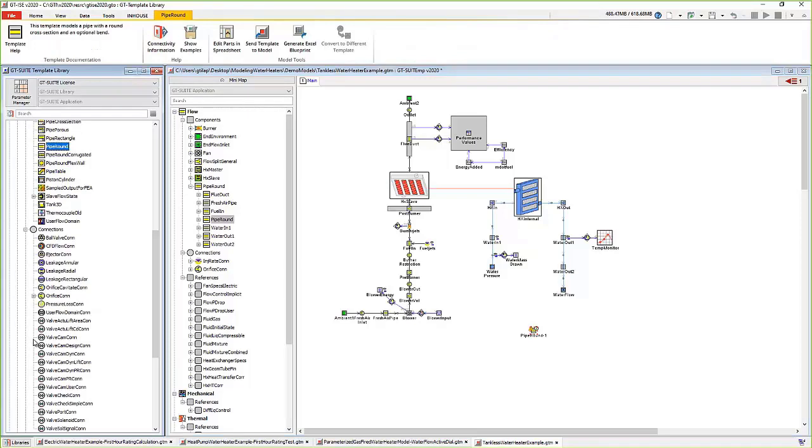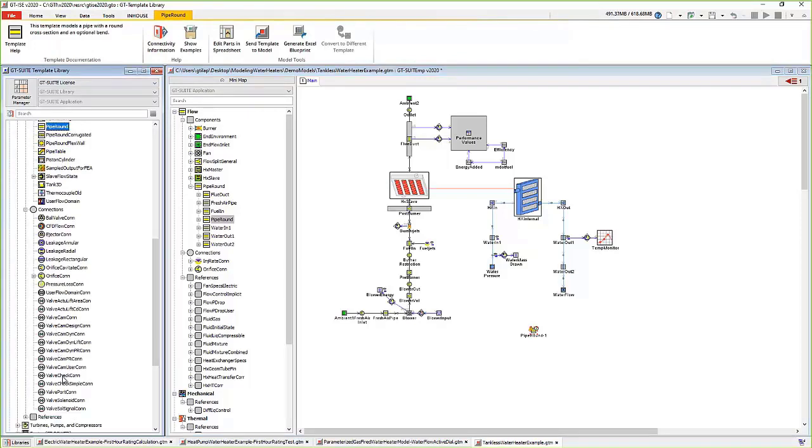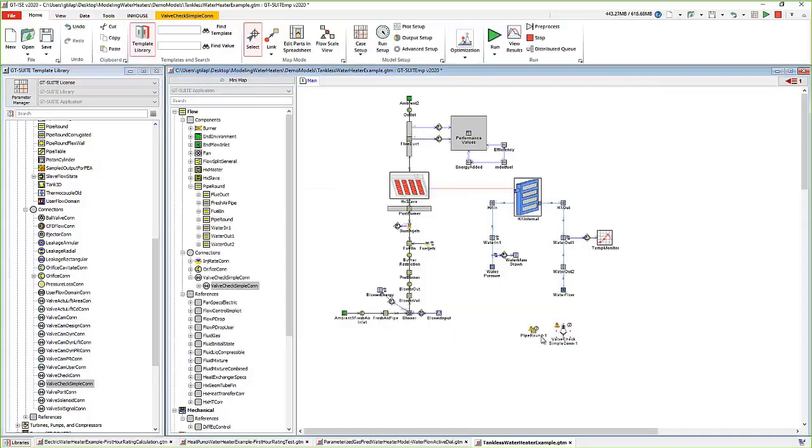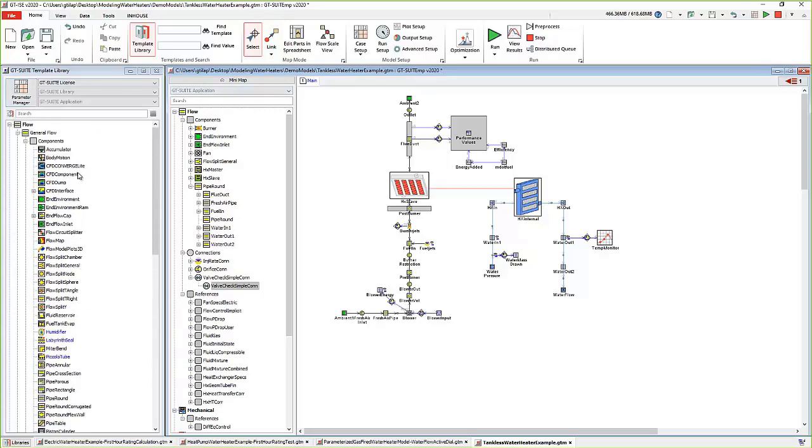And let's say maybe a user has a valve that they want to model inside their flow system. So I just take a valve and drag that right onto the map, define the inputs that go into a particular valve, and then start connecting things up using our linking option here. And so this is how you would build up a basic system model from scratch. Particularly if you don't have any CAD data available, this is the recommended approach to build a particular model, just by going by hand to put in and stitch together.